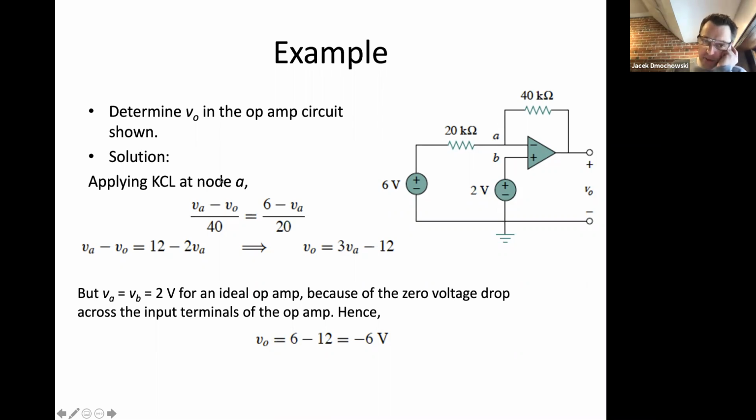You still can't tell the difference between a regular and an inverting op amp. An inverting amplifier is a regular op amp with the input connected to the negative input. The op amp is just a triangle, and that is a regular op amp, but the whole circuit functions as an inverter. So the inverter is the whole thing. The op amp, what you refer to as a regular op amp, is just this triangle. If VB was equal to 0, if we just disconnect this battery, then V naught will be equal to minus 12.